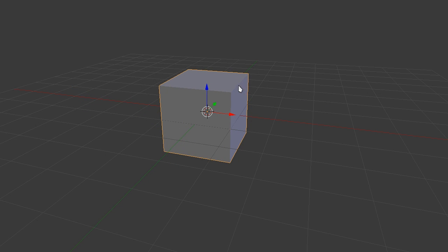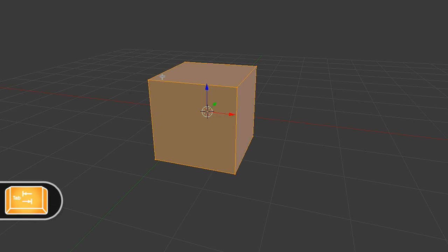to stretch out this corner, or you want to round off the edges, or do something else other than just stare at a cube. To do that, you go into Edit Mode. To enter Edit Mode, you hit the Tab key. That gives you a different view of your object. Now we're looking at the anatomy of the object.